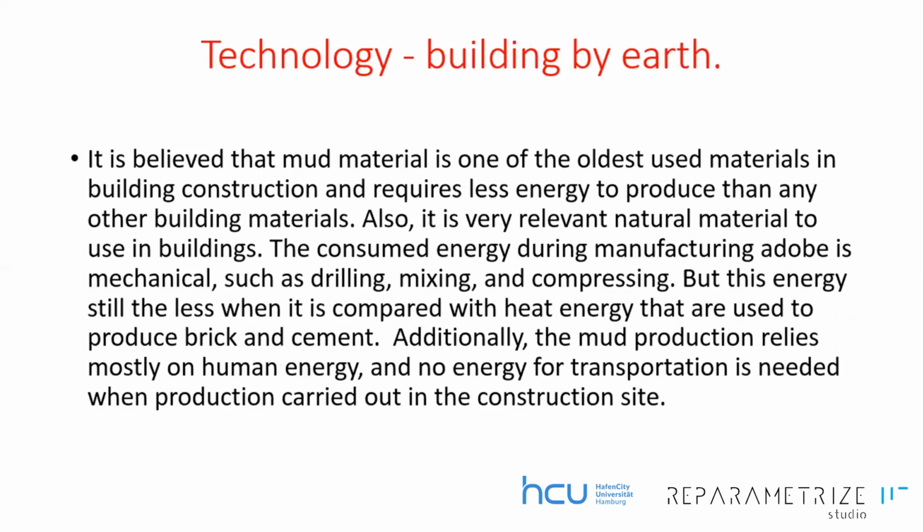Also, it is a very relevant natural material for use in buildings. The energy consumed during manufacturing adobe is mechanical, such as drilling, mixing, and compressing, but this energy is still less when compared with the heat energy used to produce brick and cement. Additionally, mud production relies mostly on human energy, and no energy for transportation is needed when the production is carried out at the construction site.